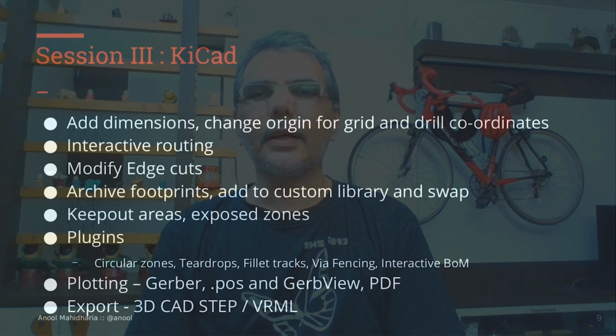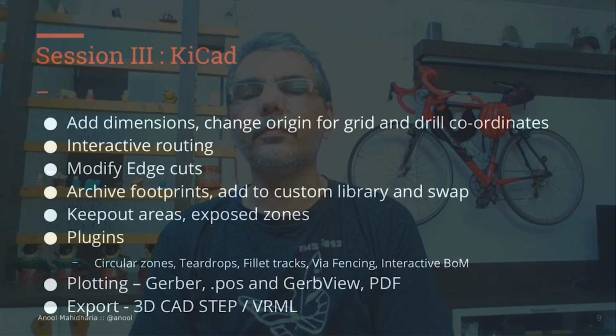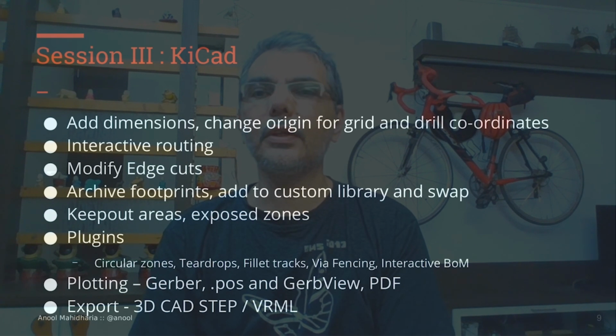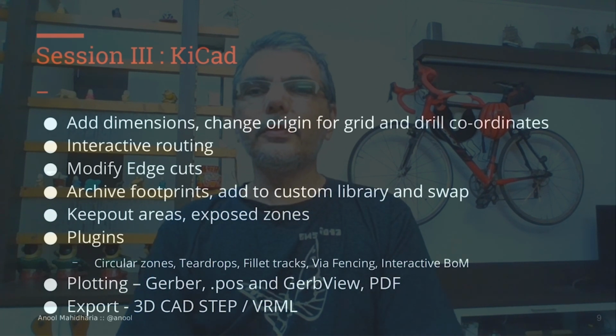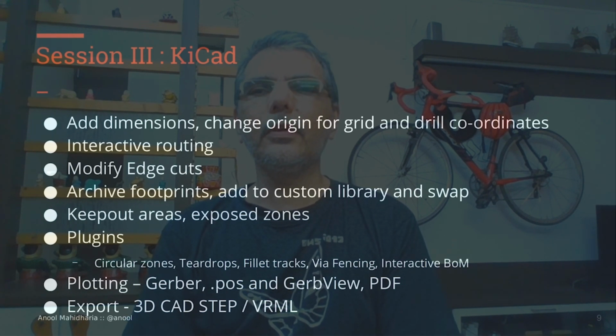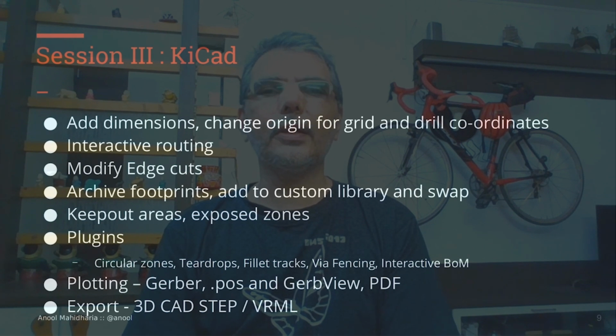KiCad has had a great explosion of plugins being added in recent years, and some of them are really very handy. So we'll look at a few of them. Once we are through with all of this, we are practically done with all of the circuit board design, and we will see how to plot our layout. This requires us to create Gerber files, and if you also plan to get your circuit board assembled, then you will need position files for all of the surface mount devices. We will view these Gerber files in GerbView before we package them to send off for fabrication.